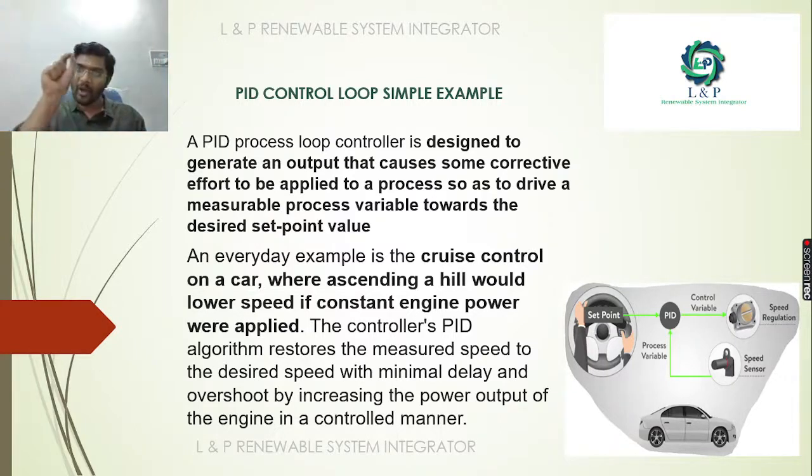Say for example, you had already programmed a fixed output: if it is 40 degrees, my damper actuator has to open this much, and if it is 25 degrees, it has to close this much. If you try to make programs like this, it will only work for fixed things. But when you are going for temperature or pressure control, you cannot expect perfect output from the sensors. So if you are receiving some input and you need to balance it, you need to make a corrective effort to make that function work properly.